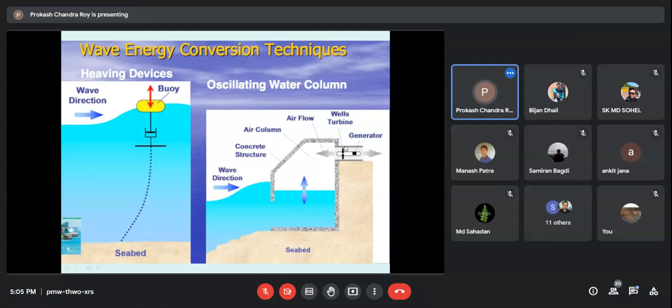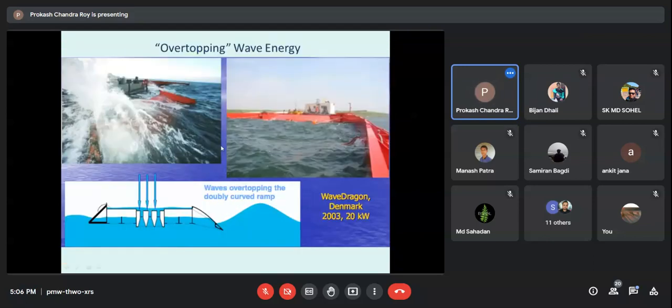If you design a turbine, it will give you mechanical or shaft power with this up and down motion of the air within a confined space through a cylindrical pipe. And if this turbine is connected with a generator, it can generate power. So the up and down motion of the water body can create flow through the passage. That is basically the oscillating water column.